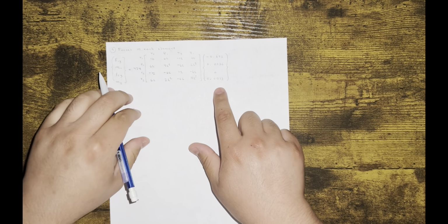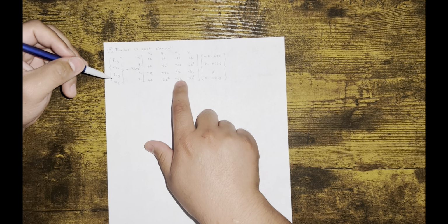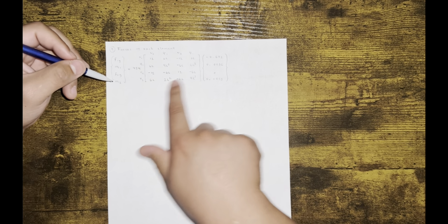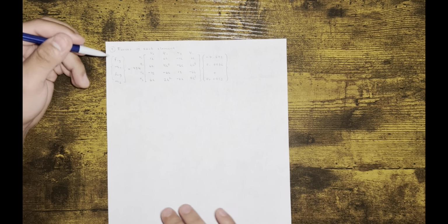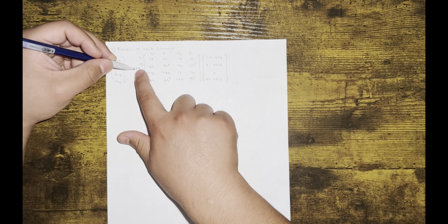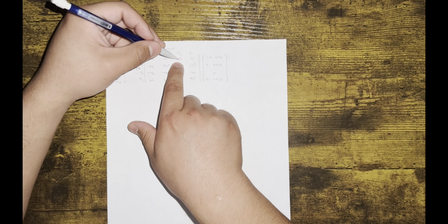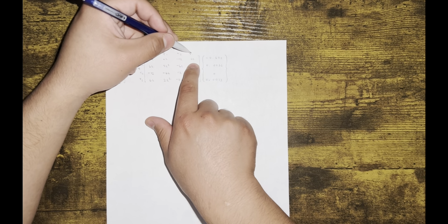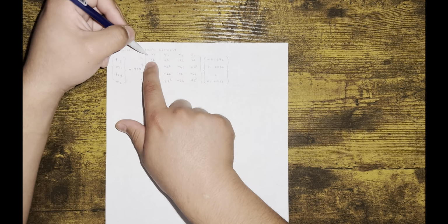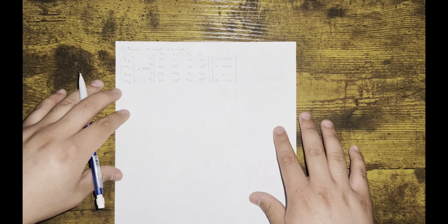Set up the matrix, right? In this case, we're looking for these four only. Where do you have these four? We know L is 240, so all this is numerical. There's no variables in here. We're done. And it's just systems of equations, right? F1y is equal to 434, 12v1 plus 6L phi1 minus 12v2 plus 6L phi1. And all these are these numbers. So let me just do it again one more time, just in case you didn't catch it.